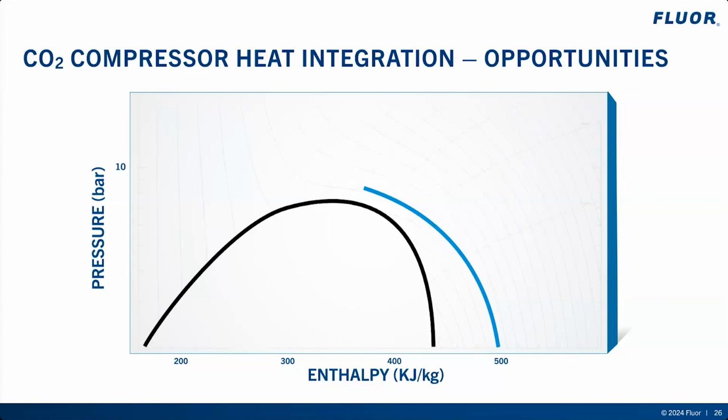For facilities and jurisdictions with relatively cheap and low carbon power but high fuel prices, shifting the compression profile to a higher cooling temperature isotherm can shift the temperature profile of the compressor cooling requirement to a heat grade suitable to offset the reboiler utility steam requirement.